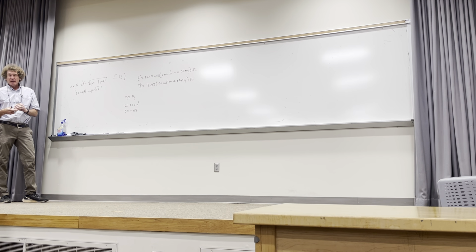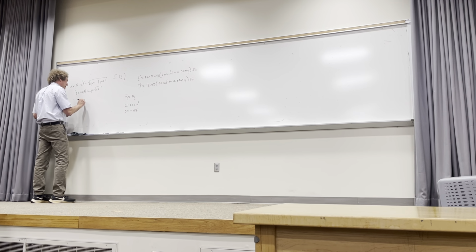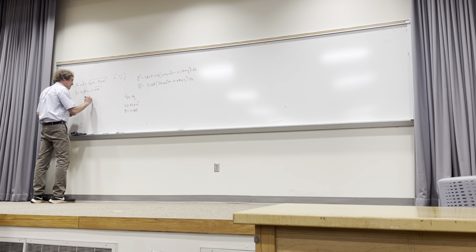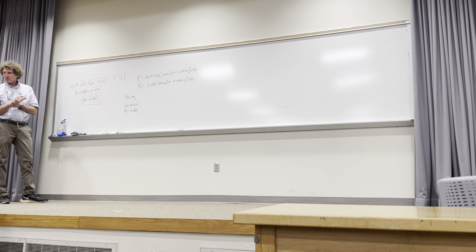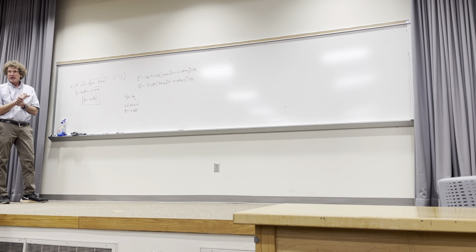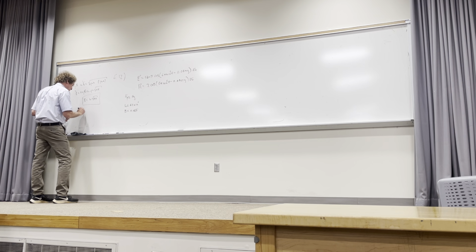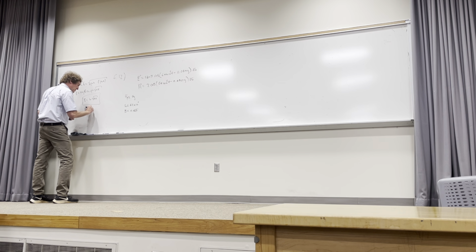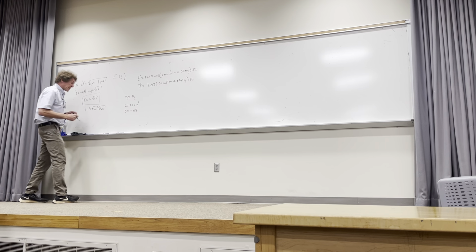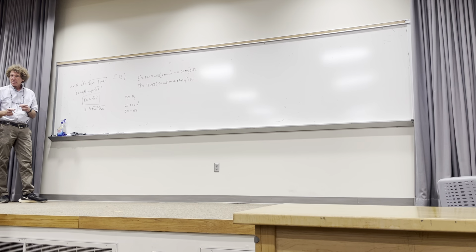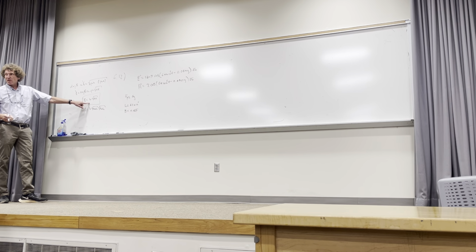Everybody? All right. I'm going to get rid of the j. Therefore, beta is simply omega times the square root of mu epsilon. Now that's always true in a lossless medium, always true for constant frequency, if it's driven with a cosine or sine. Everybody follow me on that? All right. Going a step further, beta is equal to omega times the square root of mu naught epsilon naught times the square root of mu relative epsilon relative, right? Only thing I'm doing here is making sure you see the reasoning. This is where you go to if it's lossless, always.